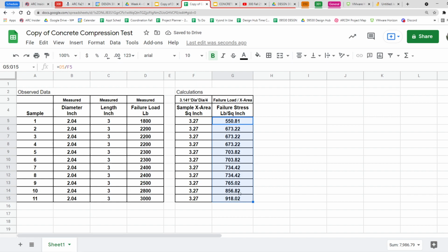So that's how much that cheapo cinder block could hold. And we have a whole bunch of them. And later on, we'll look at this and talk about averages and max and min and all that kind of stuff. There you go. Now, you look at that, you can see 1 square inch of concrete is way stronger than that square inch of soil. So we're spreading out and using all this concrete to spread the load out over the soil. So that's how you'll do this one. Okay. Here's the calculation right there. There's the calculation right there.